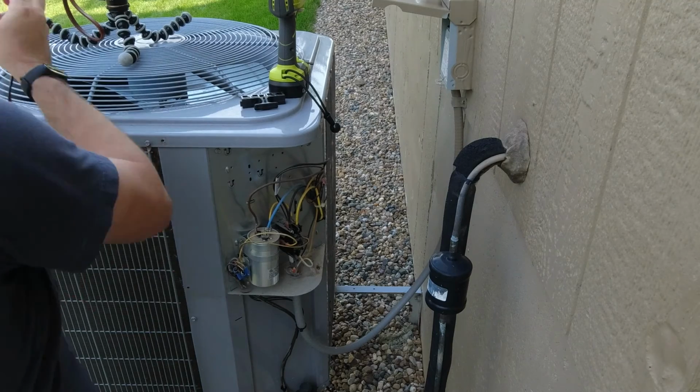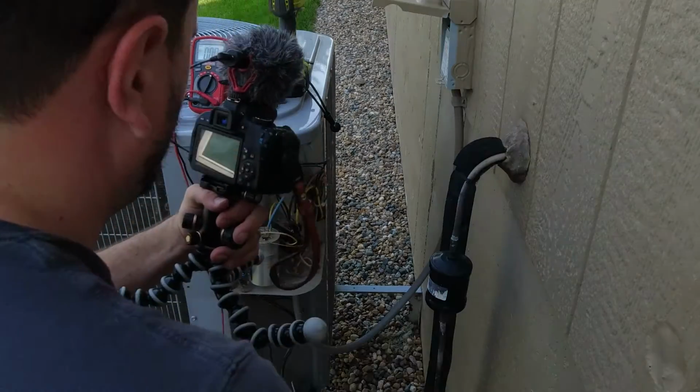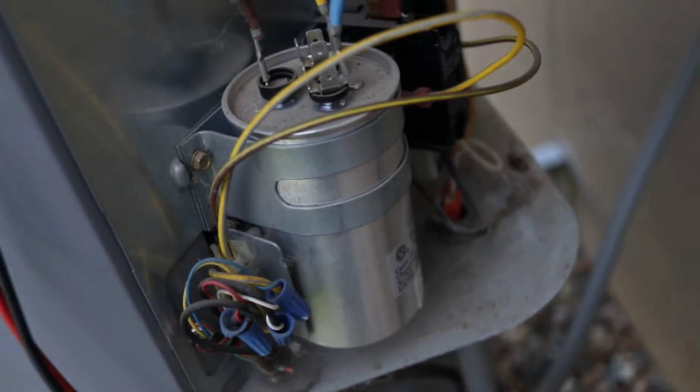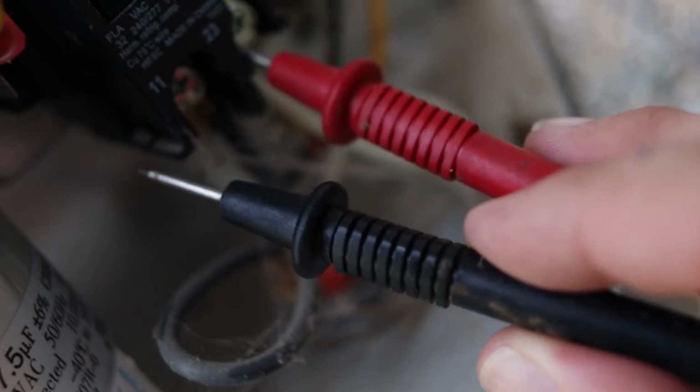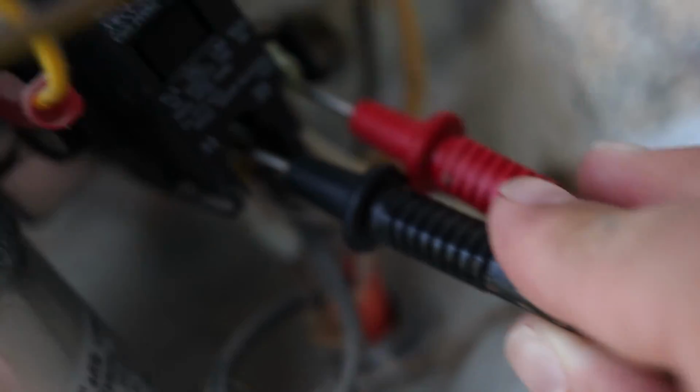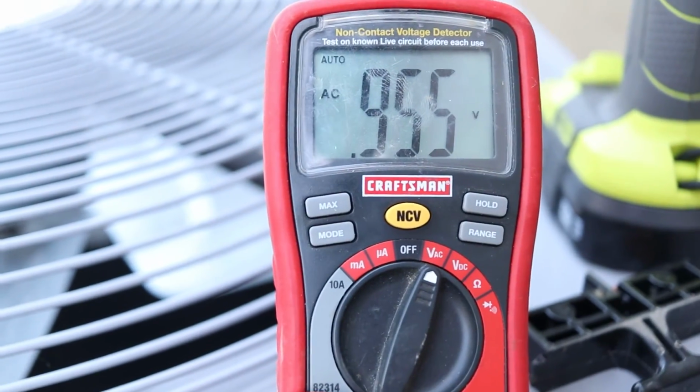So the first thing we want to do is get our digital multimeter out and make sure that there isn't any voltage in the system. So switching it to VAC, and then we'll go ahead and set this up here so it's up and out of the way. If we look here, this is where voltage is sourced from the house. It comes up through this whip here and comes out of the bottom. So the bottom half here is where we're going to check for voltage. Right here on these two lugs, we're going to put our meter here and here, like that, and we see no voltage. So there shouldn't be any voltage or current running through the system right now.